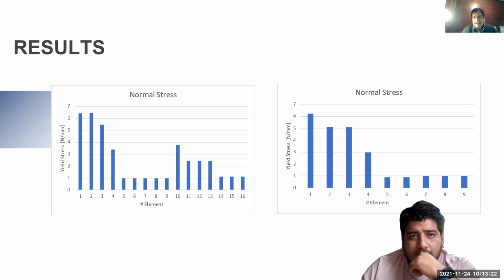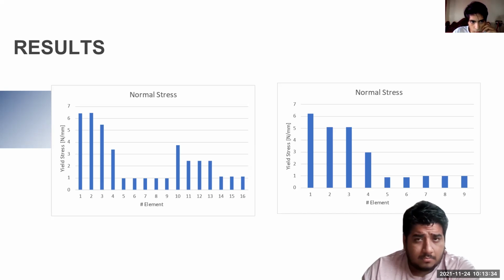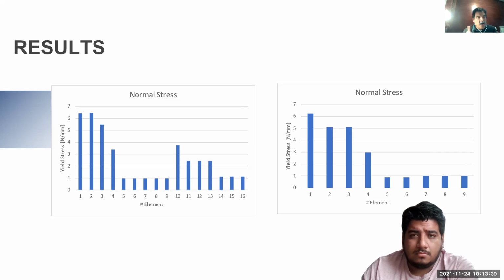And I can see that the difference of the stresses between these two elements is very small. That means that we are very close to convergence. That's what this graph is showing to me. Do element 1 and element 2 have the same value?